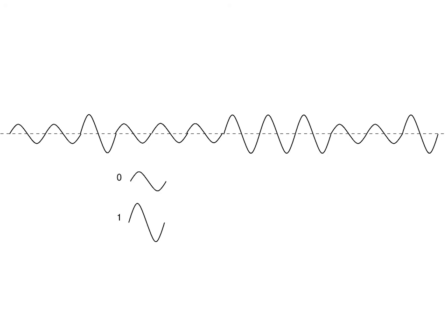Well, my diagram doesn't show greatly, but you can see at least the amplitudes, the low and high amplitudes here. We need to define the time period of each bit or each signal element. So I put some vertical dashed lines to indicate this is the duration of one signal element in this scheme. So when I want to transmit a particular bit, I send my signal for that period of time. So from that you can work out the data in this signal.